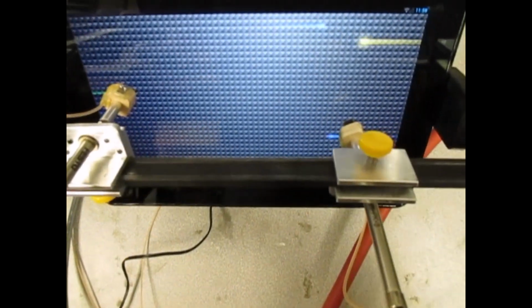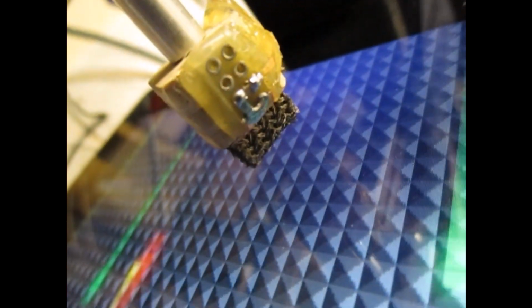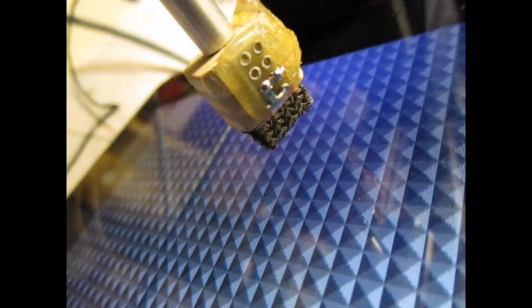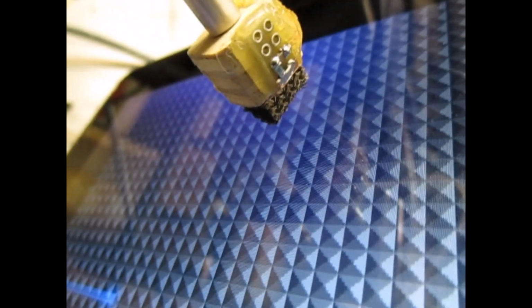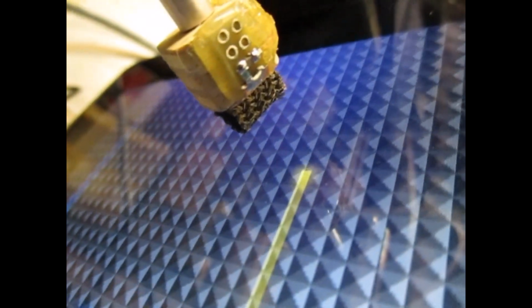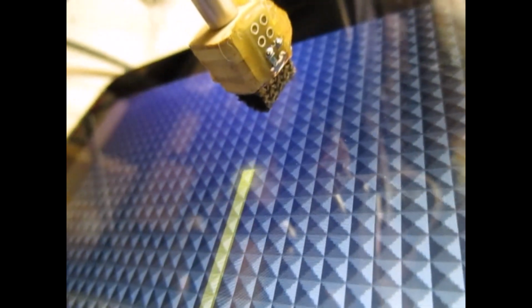Festo pneumatic cylinders, and on the tips we have the finger simulators, which is actually just a resistor and a capacitor. It's a 1.5K resistor and a 100 picofarad capacitor. It's going right to a piece of foil tape that wraps around to the front of this little square piece of plywood, and there's a conductive foam piece to provide the tip of the finger there.